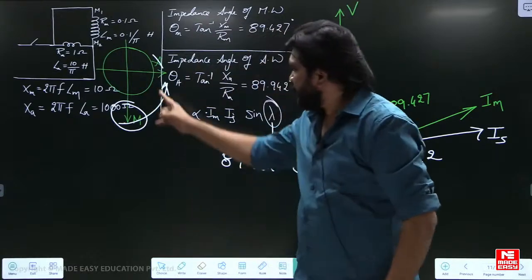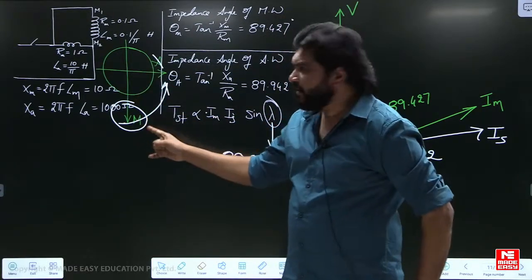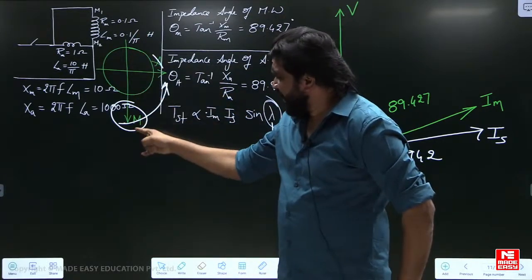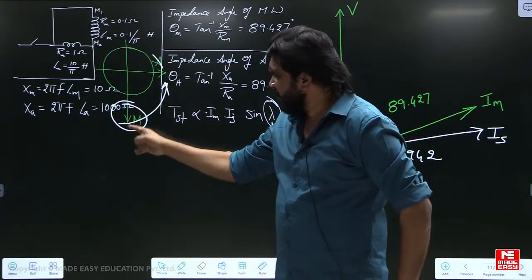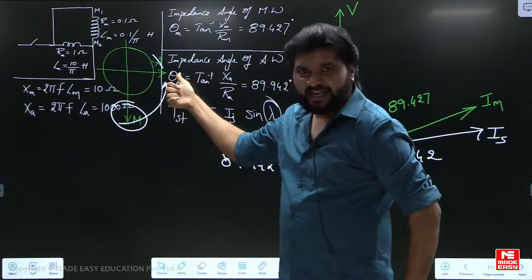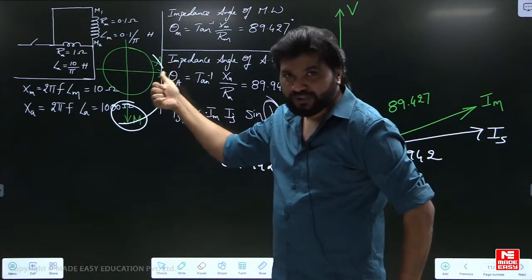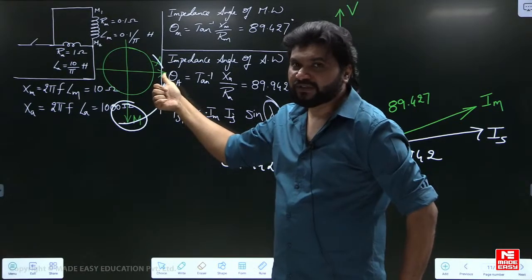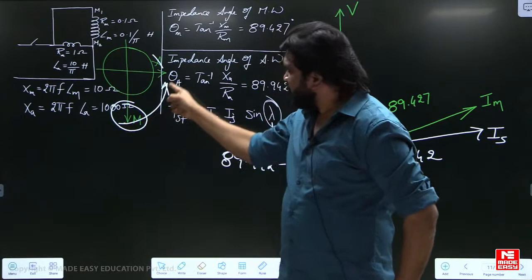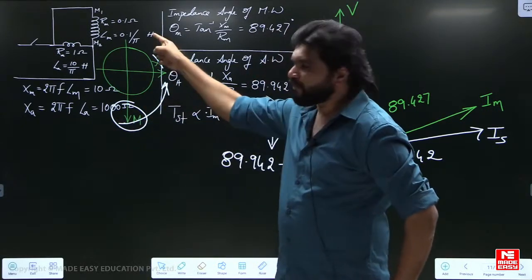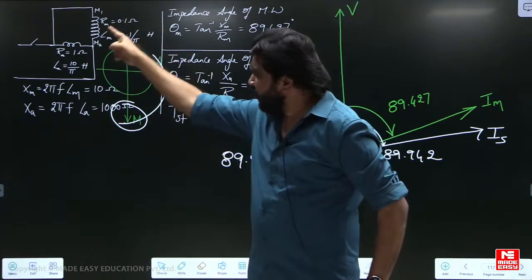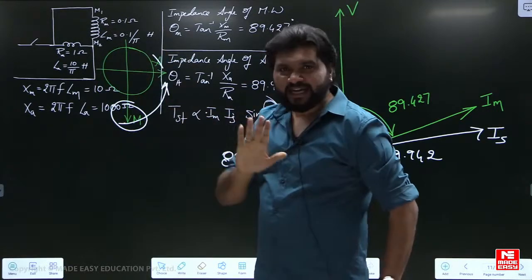So this figure will be given in the question. This is the main winding magnetic axis. This is the auxiliary winding magnetic axis. This will be the indication given to you in the question. You can check previous year GATE questions. From main to auxiliary, this is the way the flux is passing, the RMF. So the motor is rotating anti-clockwise will be the answer.